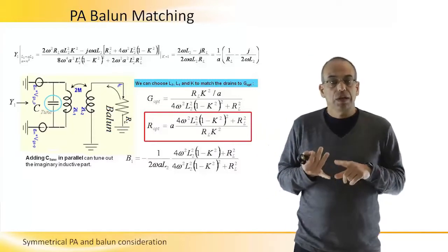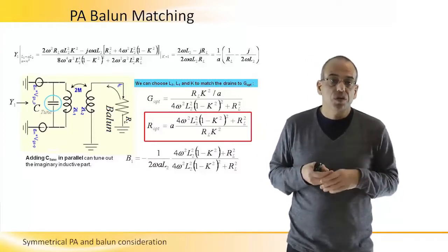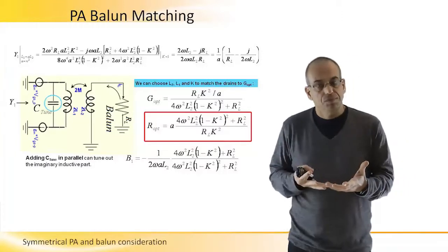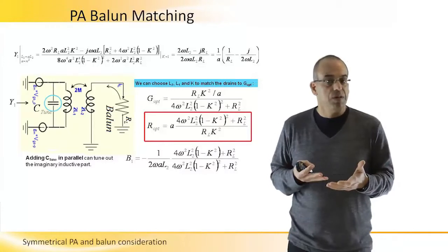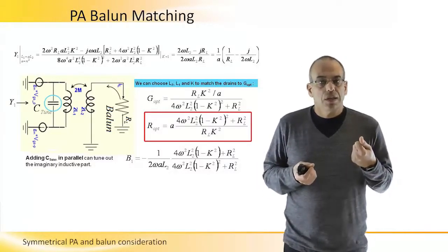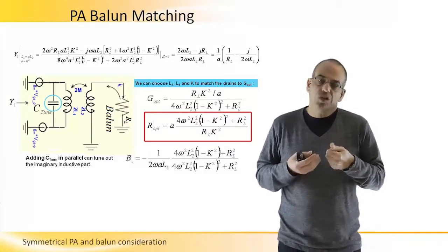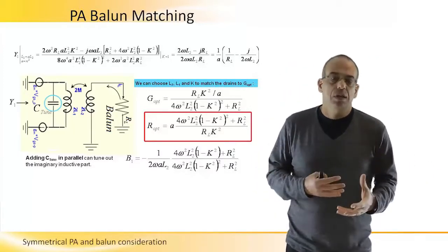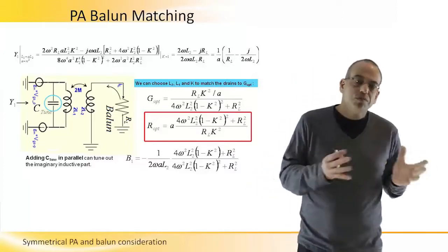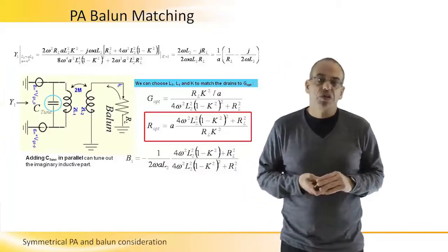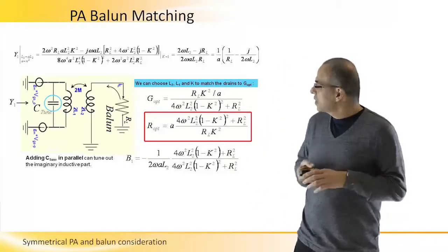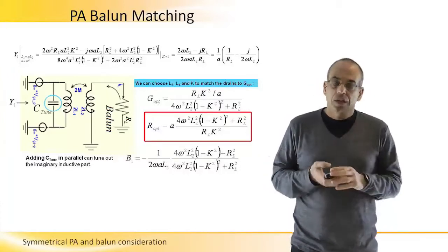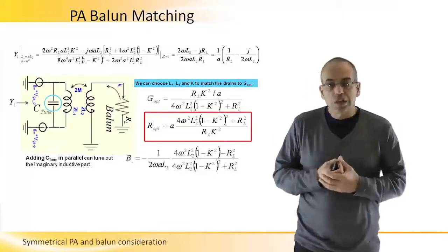We can choose here L1 or L2, the inductances, since we are left with L2 and A in this expression. We just choose physical values for L2 and also for K, because we cannot really get a K of 1 in physical design. K values of 0.7, 0.75 or down to 0.65 are more realizable physically. So one can choose the K factor, the L, and the ratio between the turns of the two sides such that our optimum will be achieved.